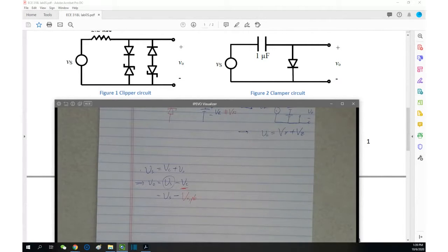Because eventually you can imagine after charging, your battery is there and there is no current, because if there's still current, it's still charging or discharging. Does it make sense? There won't be any current. With no current, the voltage across your resistor is zero. It won't help to drop down the voltage. Does it make sense?